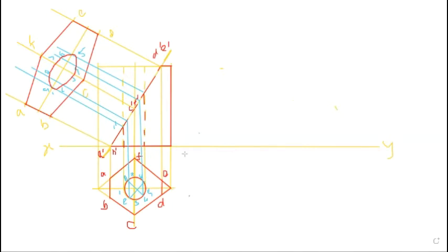For the side sectional view, when we draw, you see the lines of A, D, E, C, B very lightly different. Okay, A and D and B and D, A and E. You see, and maybe it will be merged depending upon your drawing. Okay, so A, E, both are. So you have to follow the main principle: for each point you have to draw the projection line.